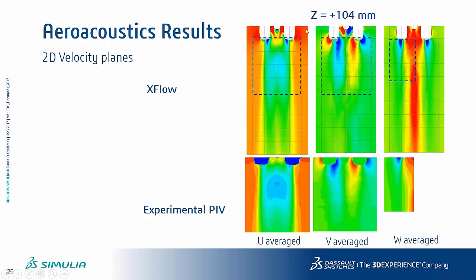Now if we change the Z direction and go to a cutting plane that is slightly above that, so we are just on top of the wheels, we've got other planes as well, so we can see here again the same comparison. So we've got the same large wake size here with some separation right there and there, with higher velocities in these areas here.